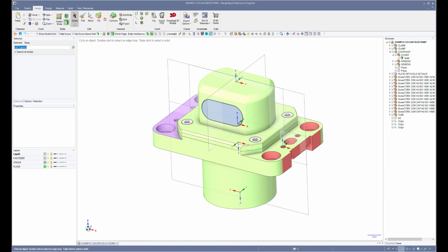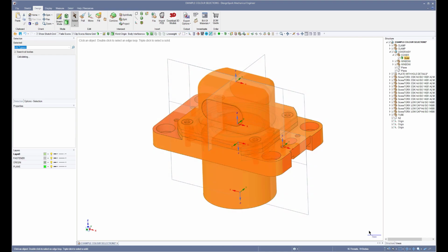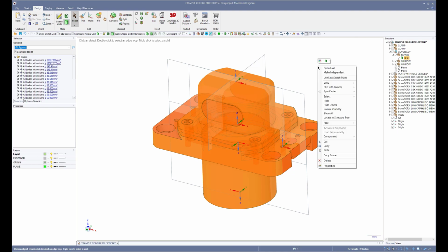And lastly, if we go to the filter command, we have a smart selection, but under that bodies is not selected. So unclick smart, click bodies, that's just a manual selection, box select. 16 threaded bodies and 19 bodies selected, right click, hide others.